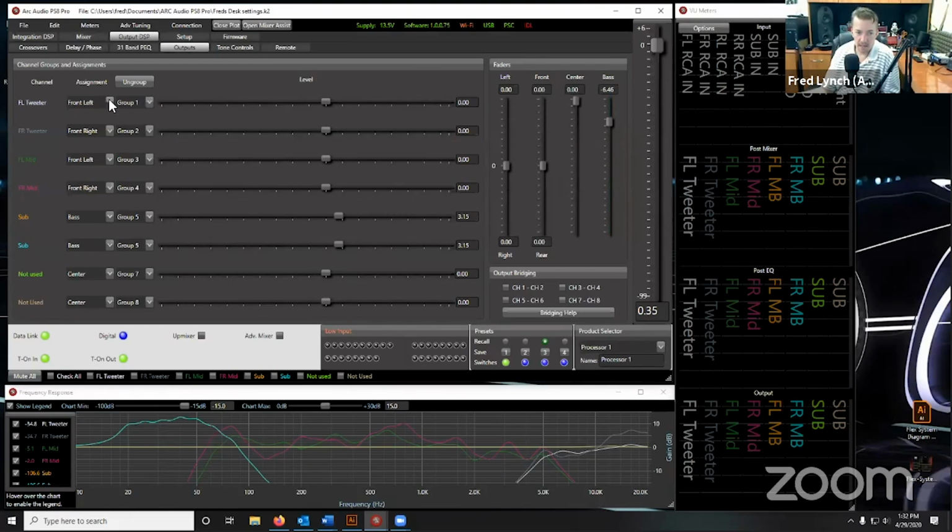If you assign these here, front left, front right, rear right, center, and base, you can select any one of these, and as long as you adjust them correctly and select the right one, your OEM controls through the PSC also work. The PSC or your OEM radio through the iDatalink AR module will allow front, left, right, rear, center, and base to function correctly.